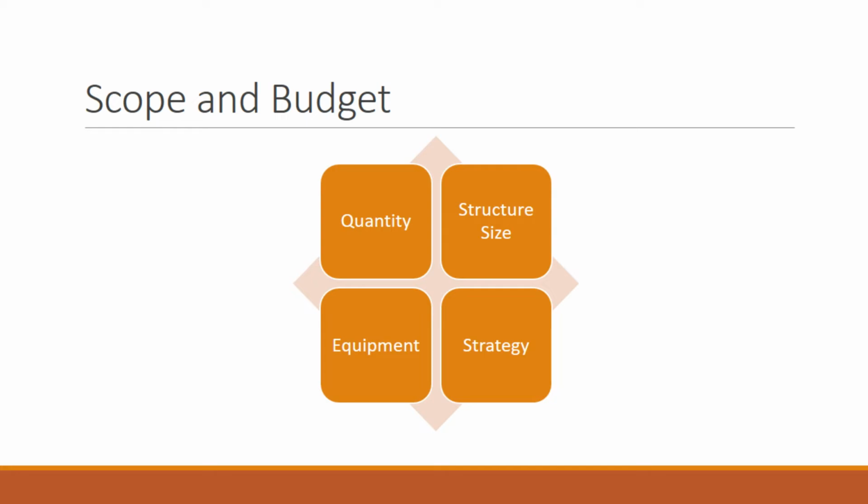Around 20 to 40% error in accuracy is typically expected at this low level of detail, and estimates are typically based on benchmarks, which are based on recently completed similar projects, experience, and a few square foot extrapolations due to the lack of detail. And to account for scope, design, and estimating inaccuracies, as well as human error and hidden conditions, a generous contingency of 20 to 40% is therefore being used.